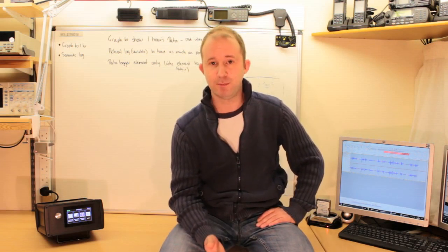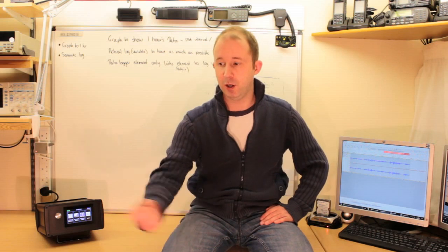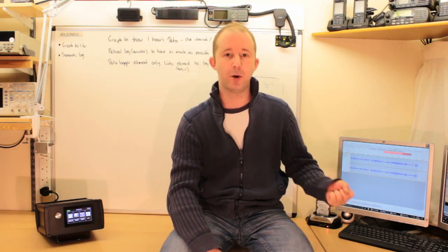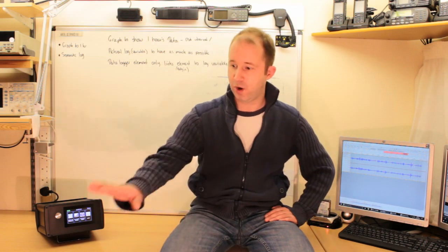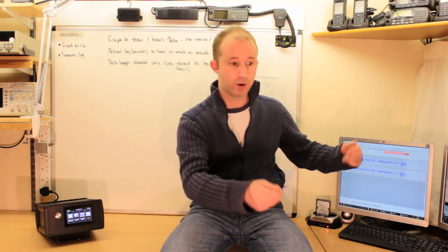Well, it's an instrument that measures the difference in pressure between 2 points. There's 2 ports on the back where you can insert a couple of tubes, and you can do what you want with those 2 tubes. One of them you can put into a low pressure or a high pressure environment, and the other tube you use as a comparison. So you can keep this one in open air and it will compare atmospheric pressure to wherever you put the other one. Or you could have 2 totally enclosed areas that are at varying pressures and compare the difference between the 2 of them.